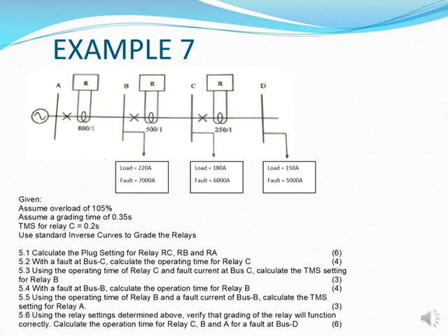It's really a very simple system that you've got, where you've got a supply source and you've got your load at D. Although you've got loads happening at your B and C, your system really shows an end point D. Therefore, we're given this, and they give you CTs between A and B, between B and C, and between C and D. And we're given the loads experienced at all of those bus bars and the fault currents at those bus bars.